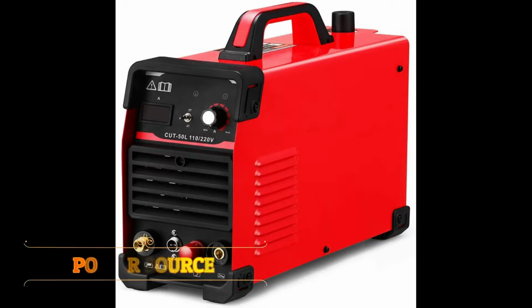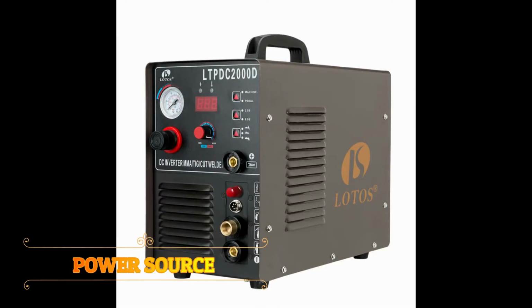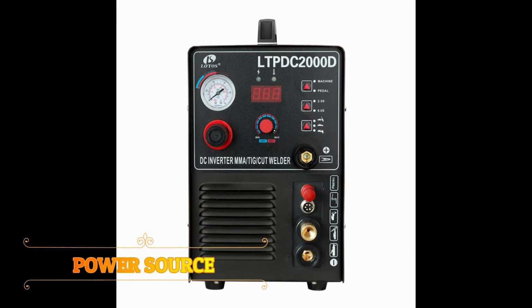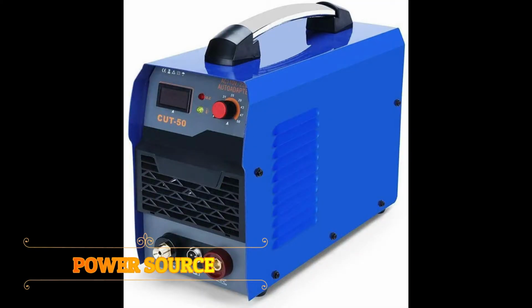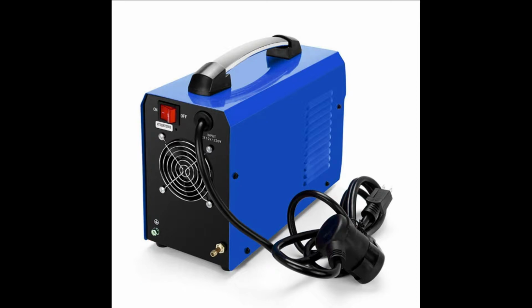Both direct current and alternating current are used for electric arc welding, each having its particular applications. DC welding supply is usually obtained from generators driven by electric motor or, if no electricity is available, by internal combustion engines. For AC welding supply, transformers are predominantly used for almost all arc welding where main supply is available.